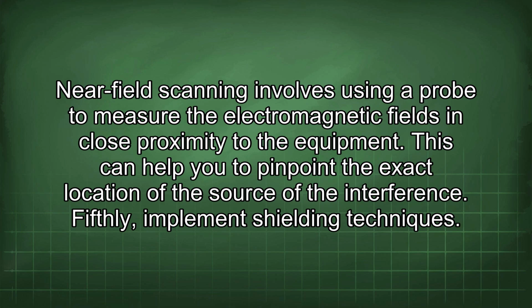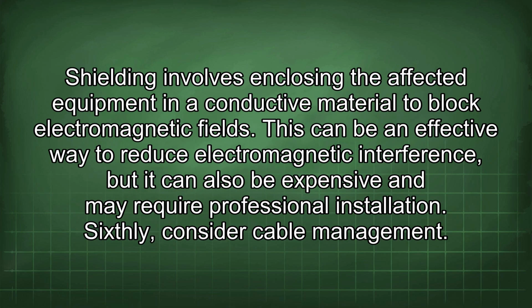Fifthly, implement shielding techniques. Shielding involves enclosing the affected equipment in a conductive material to block electromagnetic fields. This can be an effective way to reduce electromagnetic interference, but it can also be expensive and may require professional installation.